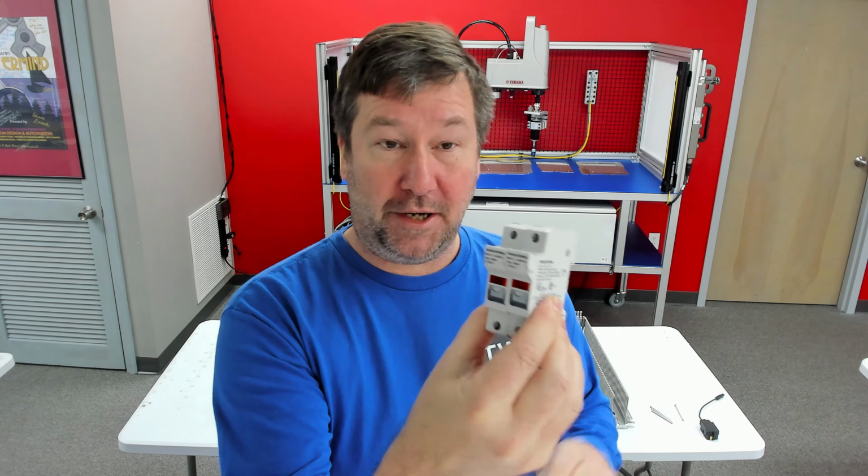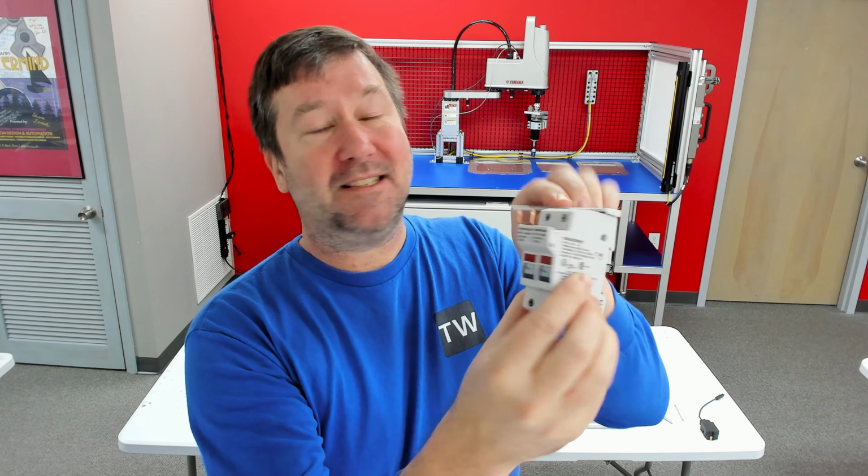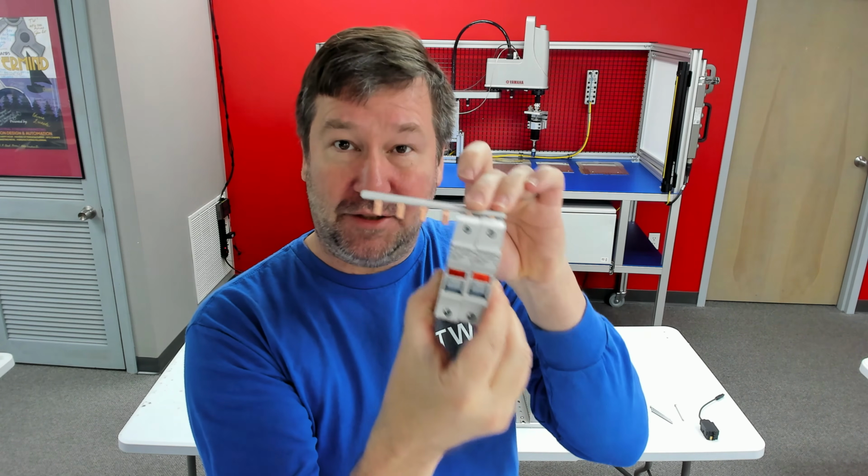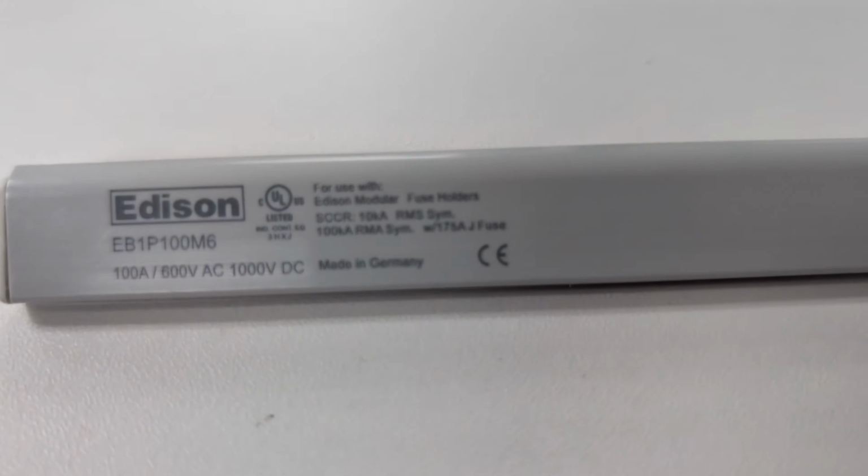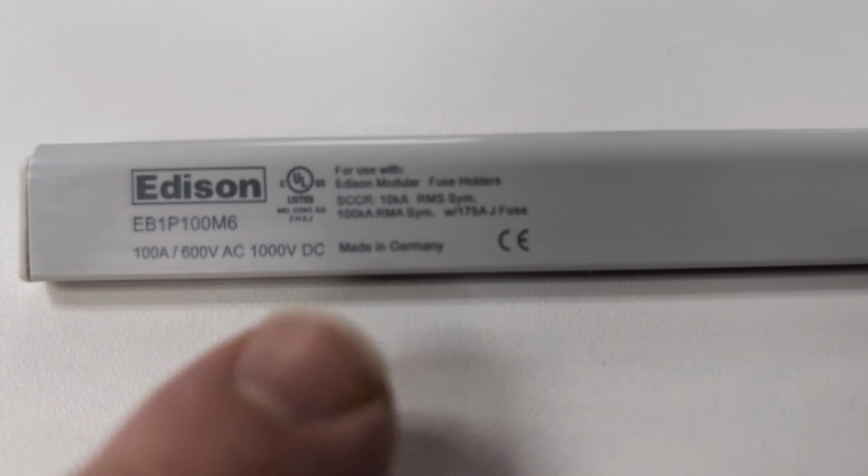And in our final example, if we have multiple circuit breakers, or in this case, fuses, this is a really convenient option to connect these. But unfortunately, if I look at the side of this device, it says the SCCR rating is 10 kiloamp. So simply by leaving a few of these devices out or swapping out a few part numbers, we can really increase the kiloamp rating. So let's talk through how we would do the kiloamp rating with what my initial thought was of how I'm going to wire this panel, and how changing certain products out increase the kiloamp rating.